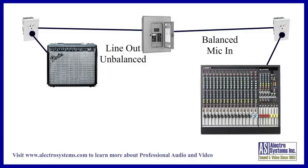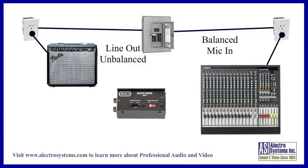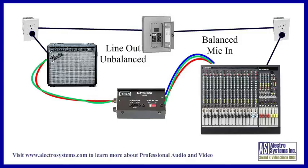The easiest way to accomplish both these tasks is to use a direct interface or DI box between the two. The input to the DI box is made for unbalanced line level, but the output is balanced microphone level. You need to keep the unbalanced input cable short, no more than about 15 feet, but the balanced output cable can be as long as you need. This doesn't eliminate the ground loop, however.